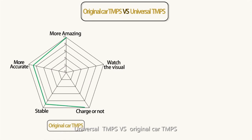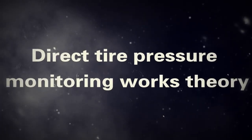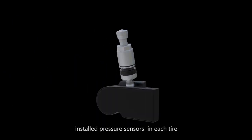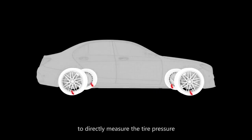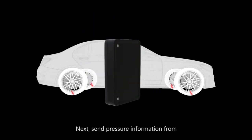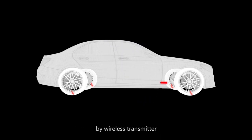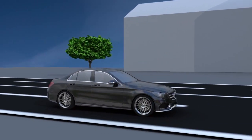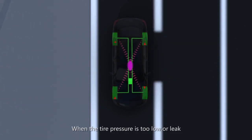Original car TPMS versus universal TPMS. Direct tire pressure monitoring working theory: pressure sensors are installed in each tire to directly measure the tire pressure. Next, the pressure information is sent from the tire to the central receiver module by wireless transmitter, and then the tire pressure data is displayed. The system will automatically alarm when the tire pressure is too low or leaking.